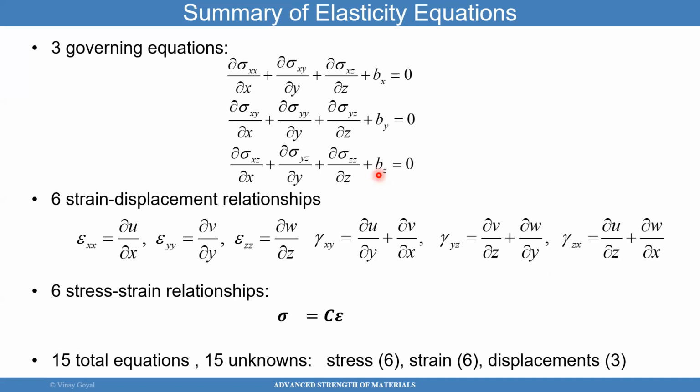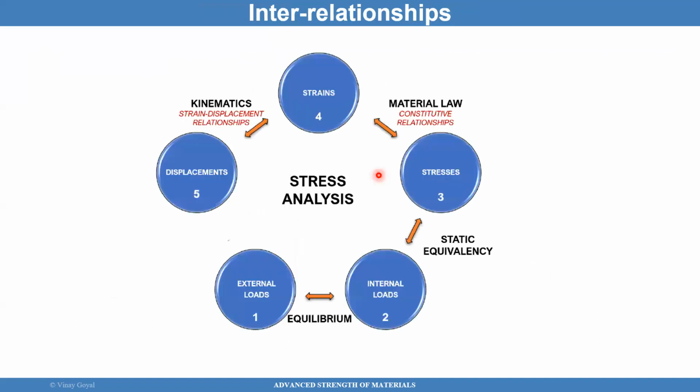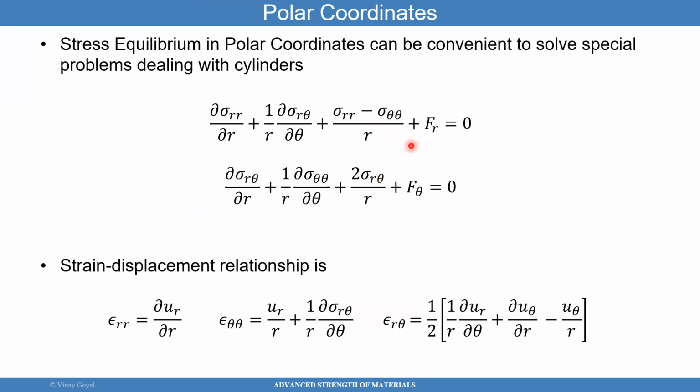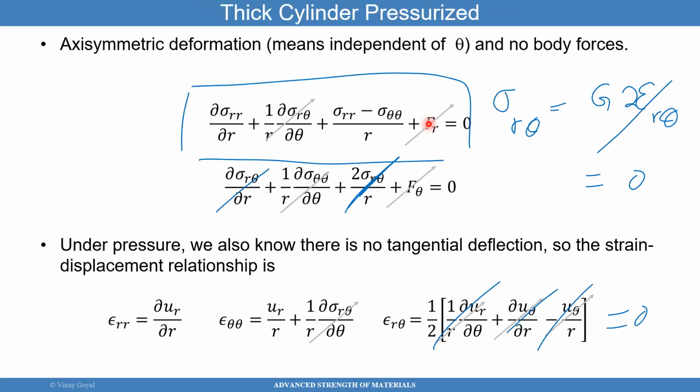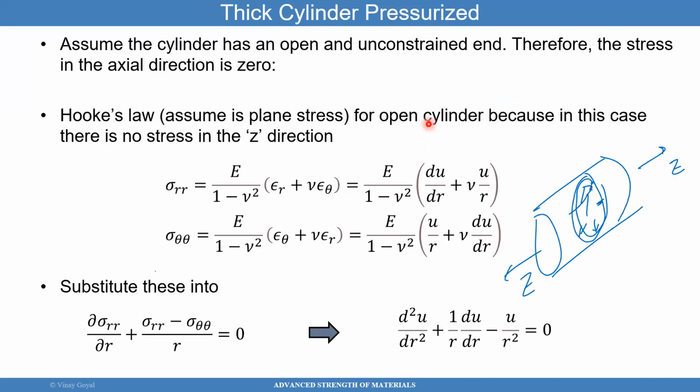But pressure, in the case of the bicycle wheel, is the wheel touching the ground, because the ground can only touch the surfaces. So again, you can only apply loads on the surface, or you can apply them to every point of the body if it's a body force. And pressure is not a body force. Does that make sense? So here you can see that putting pressure for F_R doesn't make a lot of sense, because pressure is a traction force and it's not a body force. Okay, great. I love that question. That's a great question.